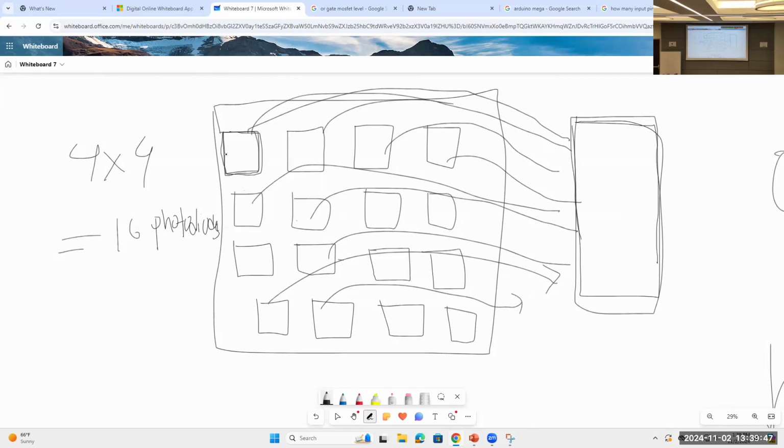Depending on the light intensity, it will give different values: 0, 0.1 volt, 0.2 volt, 0.3 volt. That's why we will need analog pins. And what do digital pins do? They take an input and give 0 or 1, nothing between. But we have to measure, because depending on the light sensitivity, the scene will be different, right?